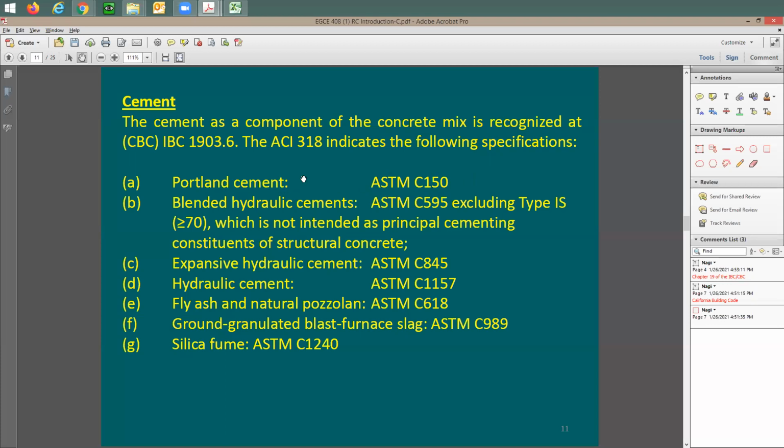For example, what does it mean by steel material for you? What's the difference between steel and aluminum? You bring here two pieces. One is going to be aluminum, the other is going to be steel. How would you differentiate between the two? There is an ASTM number, for the steel, like ASTM A615. Once you go through it, you're going to see the differences in the physical, mechanical, and chemical properties. What testing can you do to confirm that this is real A615 steel? Otherwise, you cannot really call it steel. Same thing here with the Portland cement. Each one of these is like a specification. We call this the ASTM specification, and this is what constitutes Portland cement to be Portland cement.